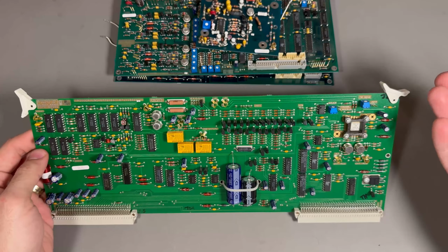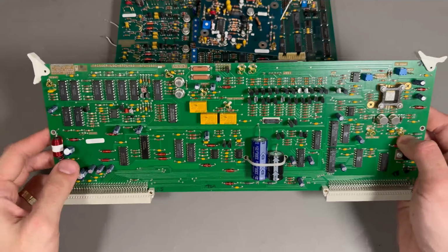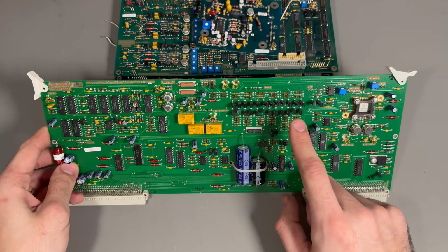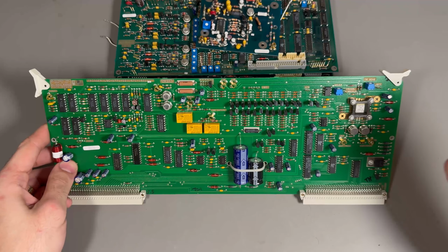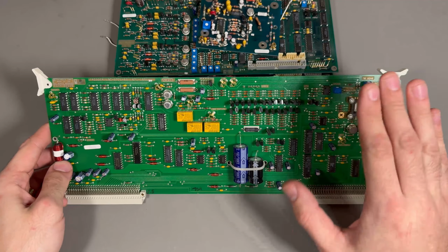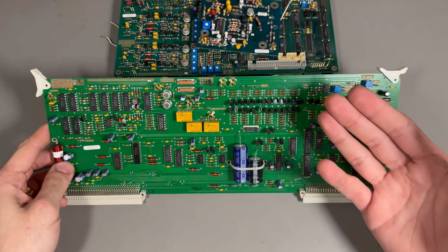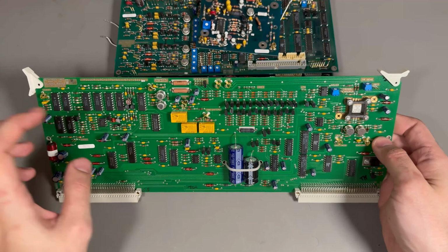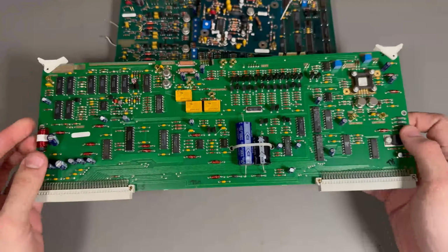Absolutely no clue what this board does, apart from the fact that it does the trigger. And as I said, or didn't say rather, the first SCD5000 that I had didn't have the internal trigger, so it needed an external trigger in order to trigger. The one that I got subsequently does have the internal trigger, and because of that, it has a bit lower bandwidth. The delay line to the scan converter tube and the trigger pickoff kind of limit the bandwidth to just 3.5 gigahertz. So you can see just how beautiful this board is, and just insane.